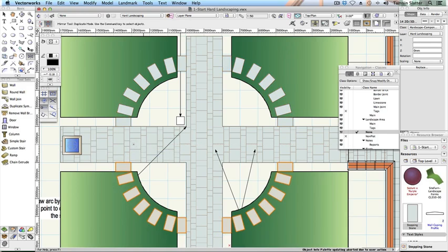The symbols have been placed on the Hard Landscaping layer, as have the lawn hardscapes. Both elements have a thickness of 35 mm. In a 3D view, their surfaces will be level, which makes it hard for Vectorworks to determine what to show. Using the View menu on the toolbar, choose Left Isometric.